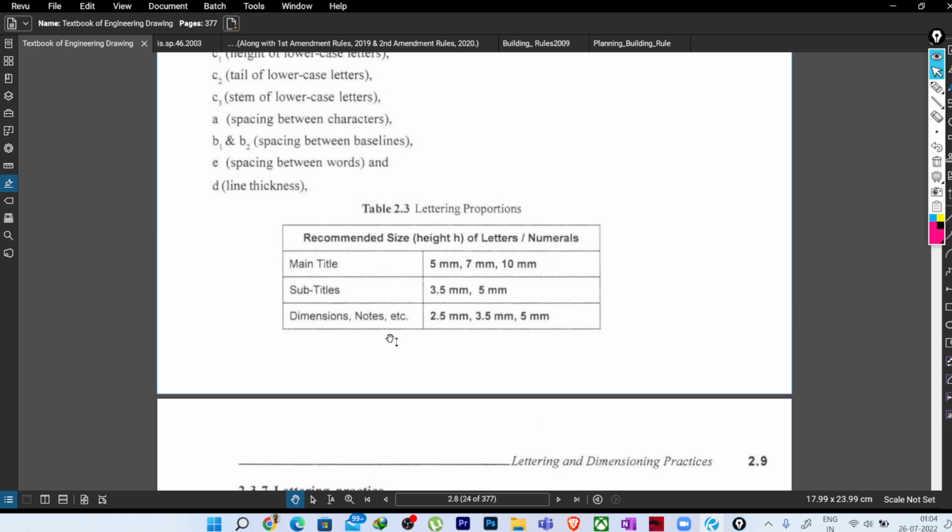But again, you need to understand, when you are making the drawing in 1:1 scale, and you will be putting this drawing on paper in 1:100 scale, then when you are scaling the drawing down to 1:100, along with this, all the texts, all the dimensions, everything will be scaling down.